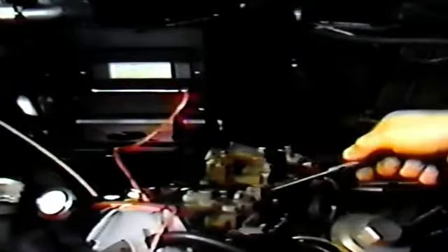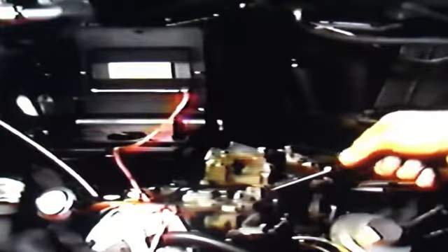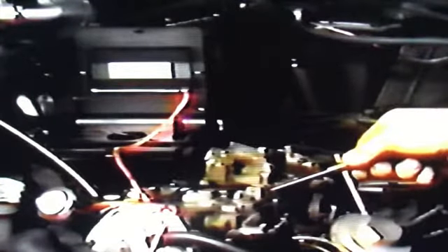The first thing we're going to do is make a throttle position sensor adjustment using the digital voltmeter. With the meter hooked up to the TPS, we'll set the TPS voltage to specifications. TPS position specs vary by carburetor. For this car and engine, the specs call for the throttle to be set at the high step of the fast idle cam and have a reading of 0.52 volts. As you can see, we're not quite there yet.